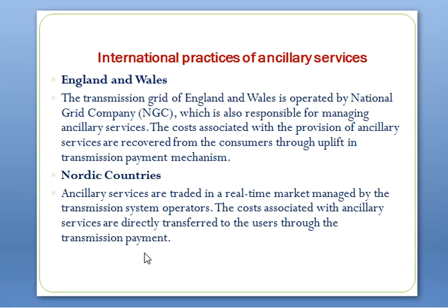For the frequency control, the system frequency is required to be within the range of 49.5 and 50.5 Hz. The service of primary frequency regulation must be provided within 30 seconds after being requested by the system operator and must be supported for the period that is needed. The required quantity is locally calculated in every country. This is an obligatory service for all the generation units, where they are required to keep a droop between 2 and 5%.